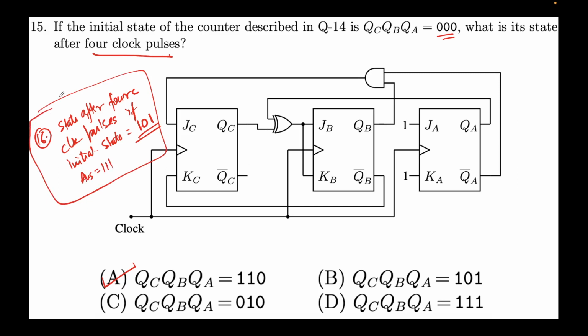All right, so we are out of time and we are also out of questions, so that is all for today. Just to summarize, today we talked about sequential circuits. First we looked at two of the very basic building blocks, the SR latch and the JK flip-flop. Then we went on to some more complicated problems like drawing the waveforms and finding the frequency of some known logical outputs. We also saw a question related to K-map, and in this question we saw how we still need to design combinational logic circuits even though we are talking about sequential circuits.